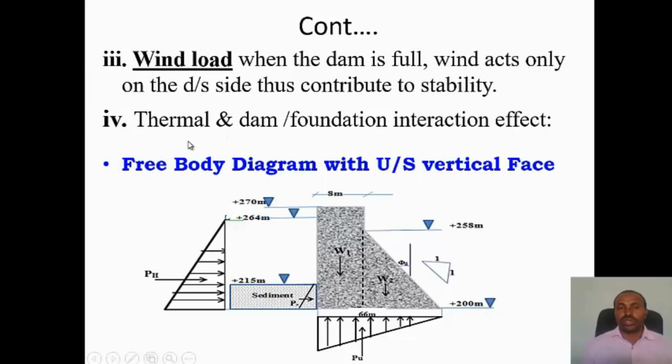So during construction, pre-cooling and post-cooling should be accomplished. The temperature in dam concrete may increase, and there is the dam and foundation interaction effect. The base contact may also be affected, foundation shear and temperature, etc.